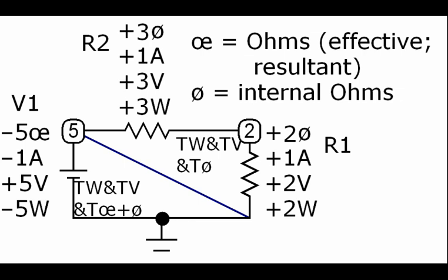And once that channel gets prepared and the voltage difference is high enough, it'll just arc over, and you've got yourself arcing going on. But that rise of voltage, there is no limit. There never is. We know that. It's the current that's the limiter. And it's the current saturation that's the limiter.